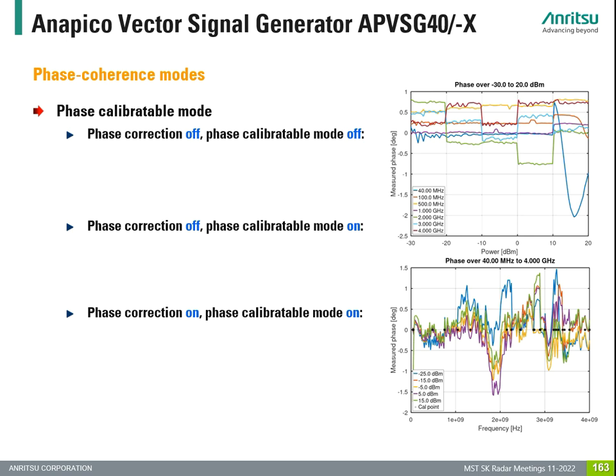Varying RF path configurations, like gain and attenuation settings, might cause jumps in the phase relationship over power and frequency settings. Therefore, phase calibration is only feasible for selected combinations of power and frequency. Covering a broader range of power and frequency would require a very high number of phase calibration points, causing prohibitively long calibration measurement times.